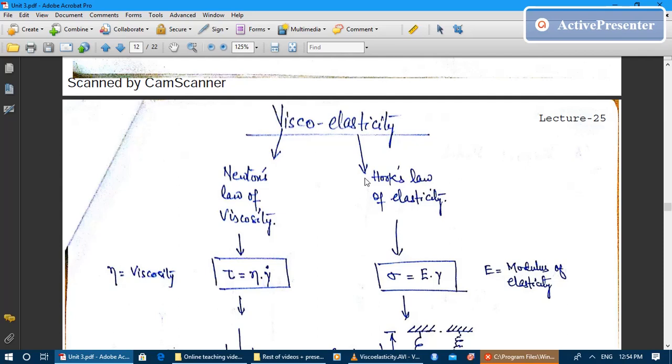So primary bonds are much stronger, and when primary covalent bonds are stretched in the direction of the pull, the bond length has to increase to accommodate this pull or push force. When bond length is deformed, it's very difficult. A lot of energy is required to pull apart the atoms in the backbone chain. So it's very difficult to distort the bond length of a polymer or any molecule.